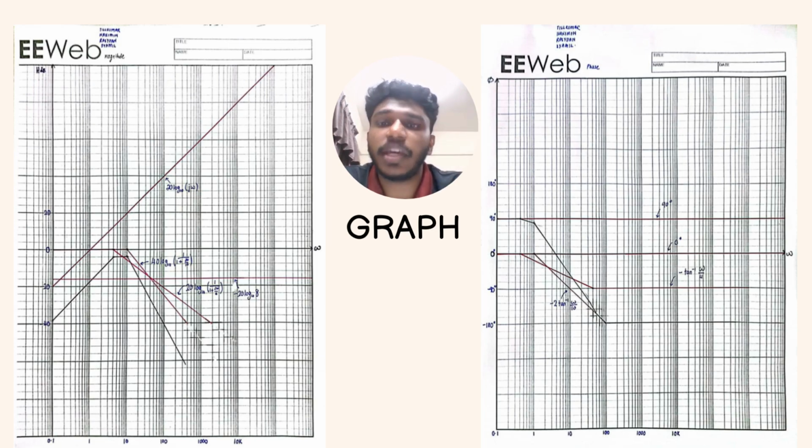I have stated there are 4 lines: for the 20 log j omega, and for the 40 log 1 over 1 plus j omega over 10, and also for the 20 log 1 over 1 plus j omega over 4, and also the negative 20 log 8. So I will start off with the 20 log j omega. For the 20 log j omega, its start point will be from negative 20.